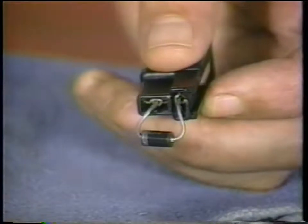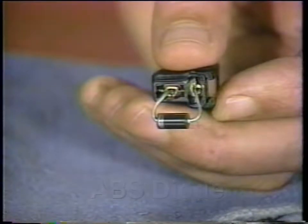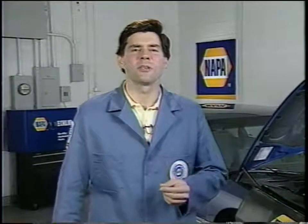The system includes an ABS diode, which functions as an electronic check valve to help prevent EBCM damage should voltage be introduced on the wrong side of the circuit. This could happen if an electronic component fails or there's a short in the circuit.